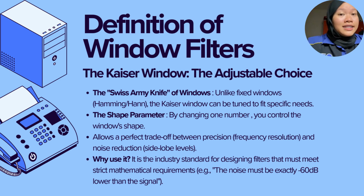Next, we have the Kaiser window, which we often call the Swiss Army knife of windows. It is highly adjustable, unlike the fixed Hamming or Hann. The key here is the shape parameter. Using one number, engineers can control exactly the shape of the window. This is because a perfect trade-off between precision, which is our frequency resolution, and noise reduction, which speaks for side lobe levels, can be achieved.